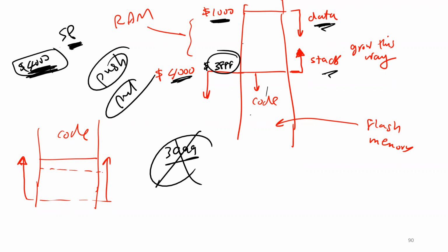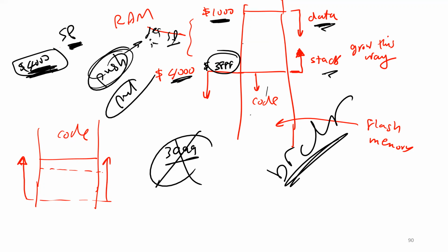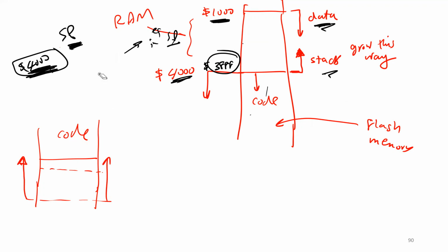Do you remember when I said, for example, about branch if clear, that this instruction is going to do three operations in one instruction? This is the same thing. This one is going to decrement or increment the stack pointer, and it is also going to write. So you don't need to worry about the stack pointer. Once you initialize it at the very beginning of your program, just leave it. Any questions?